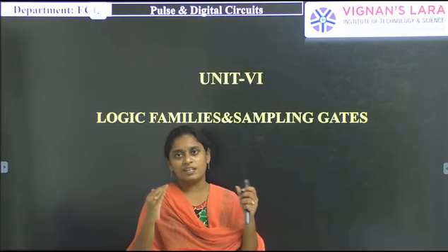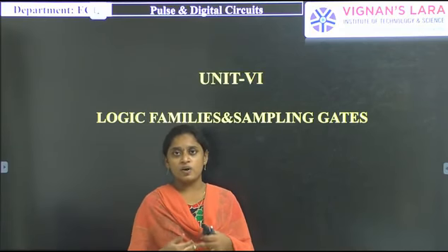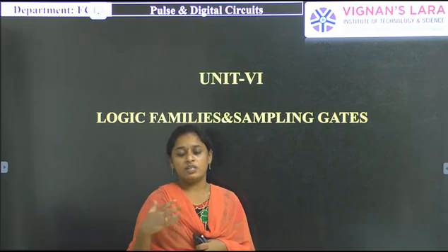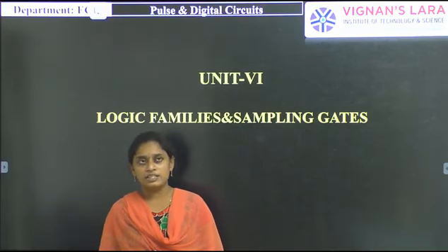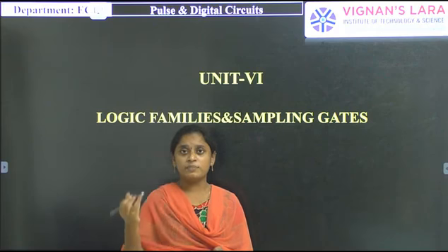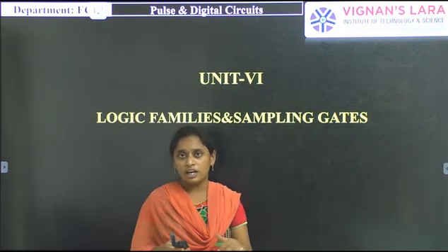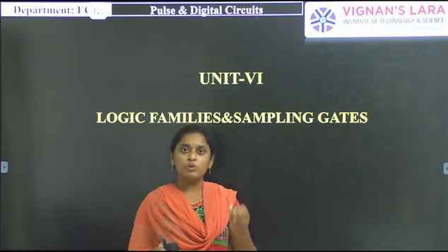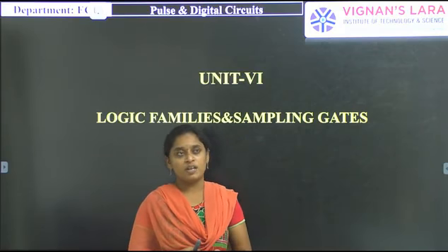Why? Because noise margin is simply the extra noise added to that particular logic family which can't affect the circuit. That is known as the noise margin. Here the noise margin is very less for the ECL logic family, and at the same time there is the problem of cooling. The problem of cooling simply indicates that it is easily heated. That's why we have to cool that particular ECL logic family many times. That is a problem of the ECL logic family.